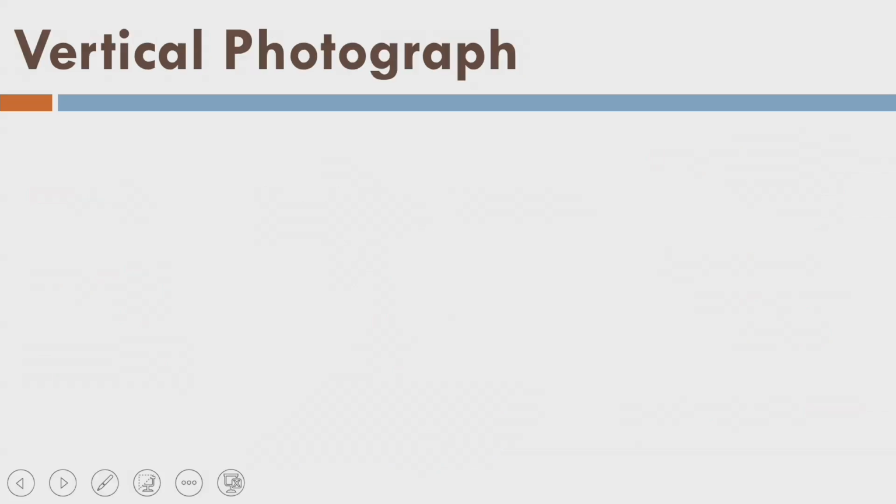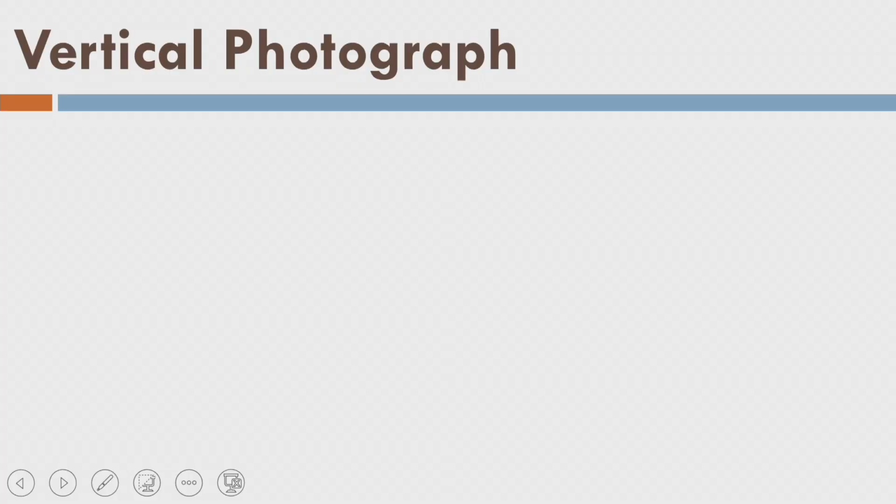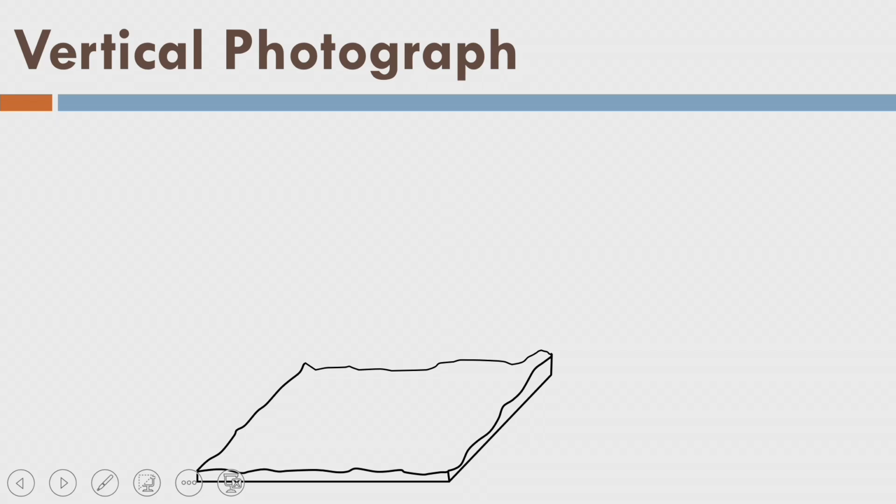All right. Let us come to the vertical photograph now. In the previous slide, I assumed that the camera optical axis and the Nadir line, or the gravity line, are matching. Let us look into what that means. So, let us say there is a terrain where this distance is nothing but a swath, for example.